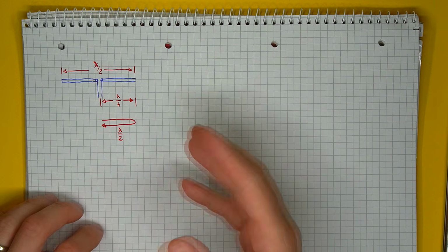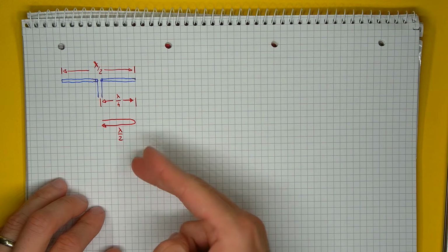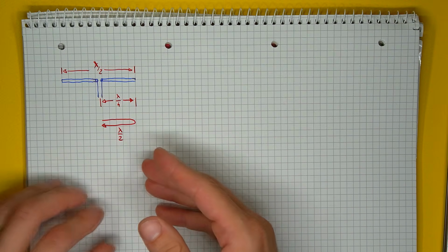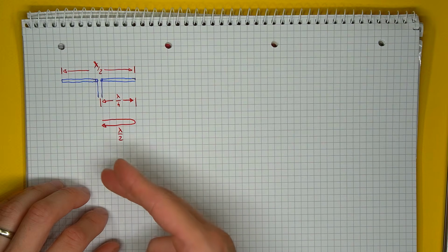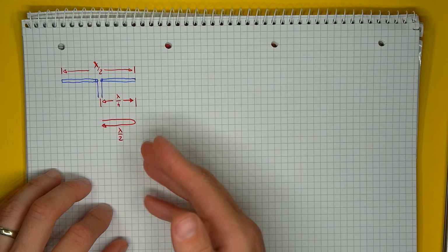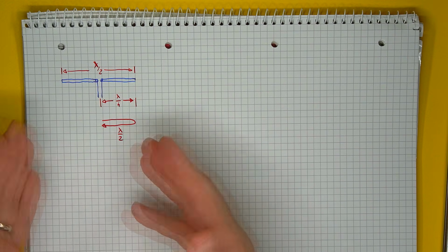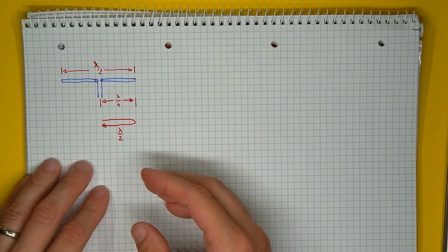So why isn't the resonant dipole antenna exactly a half wavelength long? Or why should it even be in the first place? Well, the general theory around the half wavelength point is that at this specific dimension, the wave traveling through each quarter wave section of the antenna will bounce back from the end and be in exact phase opposition with the incoming wave. There will be a half wavelength delay, or 180 degrees. This will cancel out any reactive elements, and the antenna should have only radiation and loss resistance.